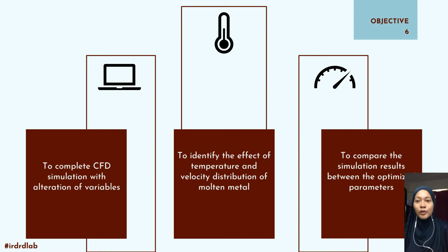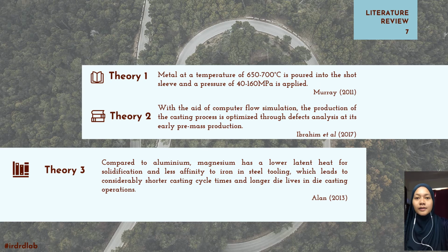CFD analysis is one of the best analyses. The second objective is to identify the effect of temperature and velocity distribution of molten metal in the plunger. And lastly, to compare the simulation results between the optimized parameters. By using the computer-aided flow simulation technique, it enables engineers and designers to construct a new method to analyze casting defects at an early stage of mass production.